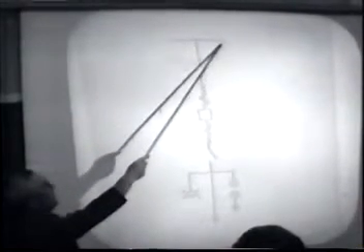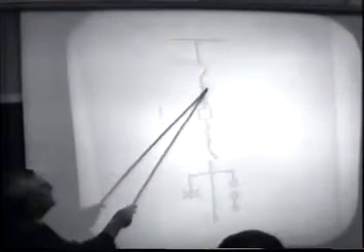And you can see the path of energy transfer from the bus up here down through the disconnect switches, the circuit breaker, the other disconnect switch for the breaker, out onto the circuit. In this particular case, we've shown surge protection by a lightning arrestor and an auxiliary unit in the way of a potential transformer.